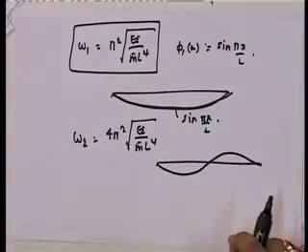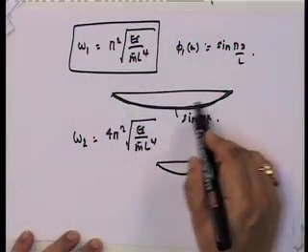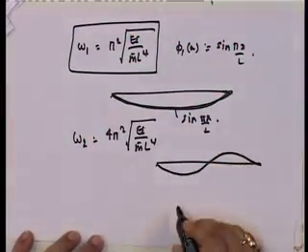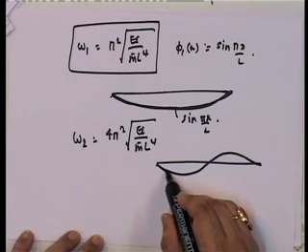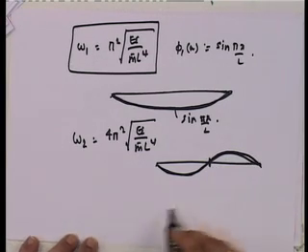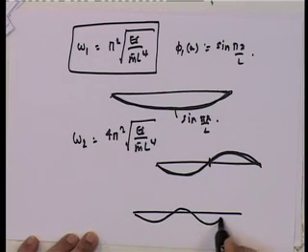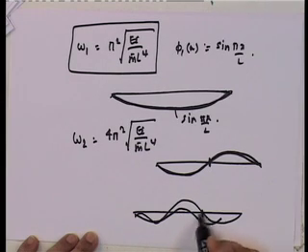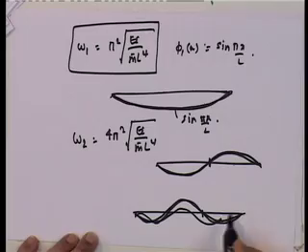But note again one fundamental point that I made last time. First mode: lowest strain energy, no node. Second mode: slightly higher strain energy, one node. Similarly, the third one has 2 nodes, a higher strain energy mode. So, the point remains that the fundamental mode has the lowest strain energy mode shape, and as you go higher, the strain energy goes up, and so on and so forth. So, this is for a simply supported beam.